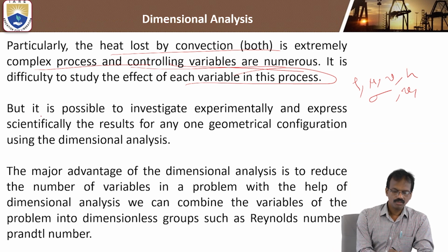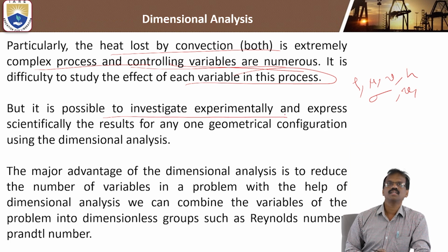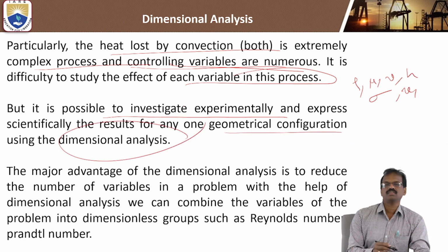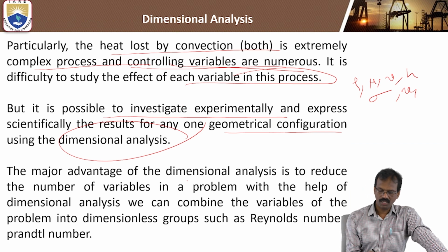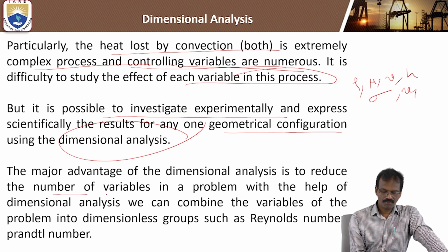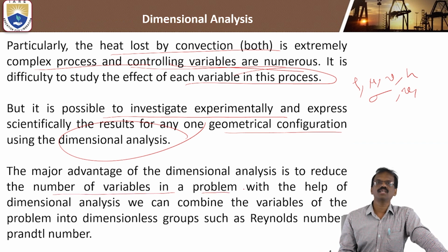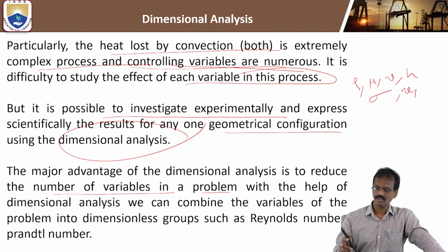So it is possible to investigate experimentally and express scientifically the result for any geometrical configuration using dimensional analysis. That is the main purpose of dimensional analysis. The major advantage of dimensional analysis is to reduce the number of variables in a problem, so we can combine the variables of the problem into dimensionless groups.